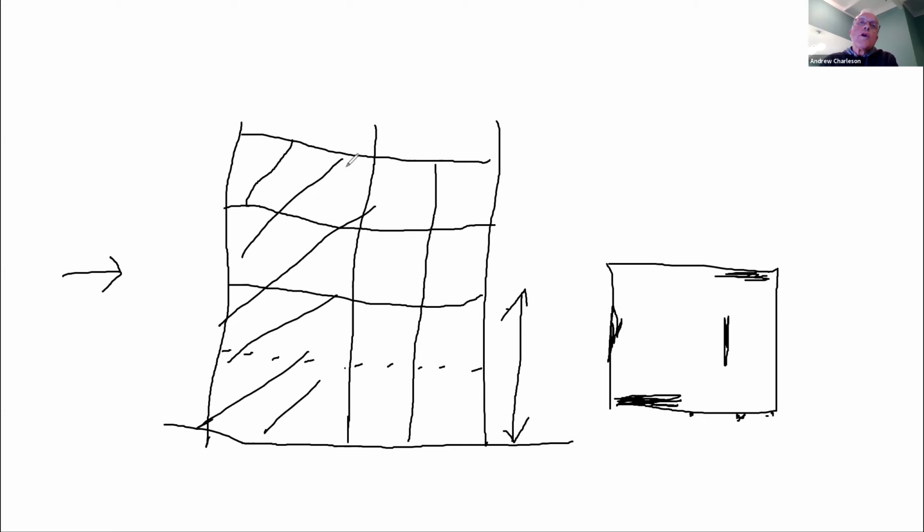And so here's the shear wall, and it'll have a strong foundation beam, and it'll probably have tension piles underneath it. So that is the normal solution to solving a soft story. Don't use moment frames, use shear walls to resist earthquake.